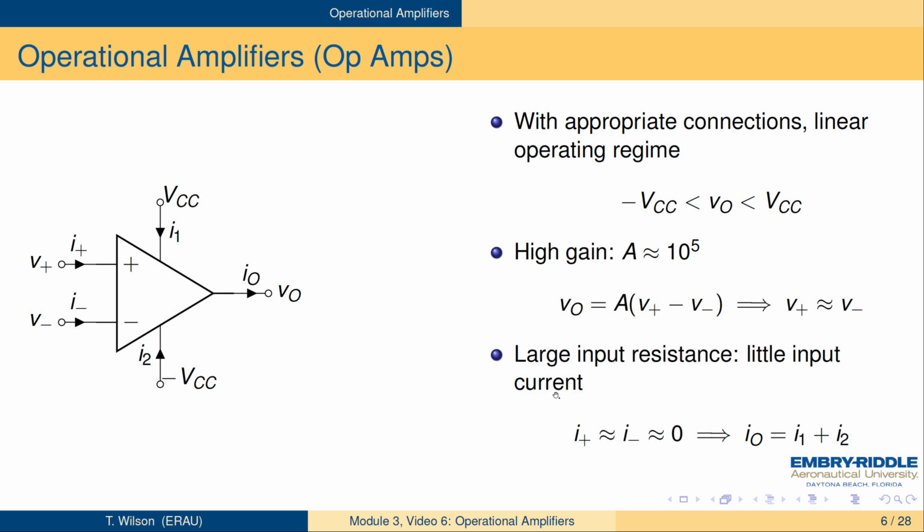Since there's little current coming in or going out of the inputs, those currents are approximately zero, which means that all the current going out comes from the supply terminals. And that sort of makes sense. That's the whole idea here.